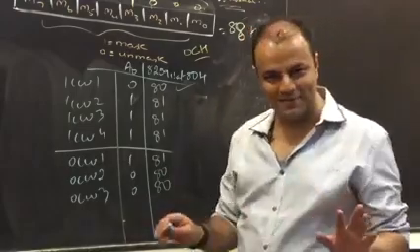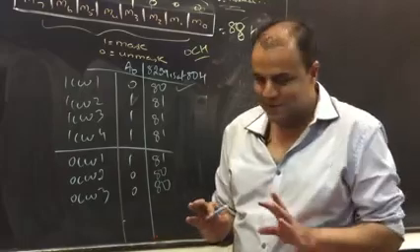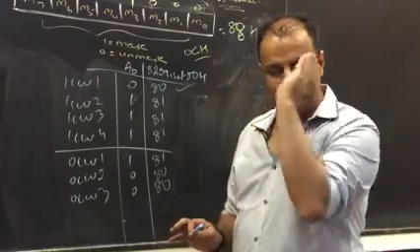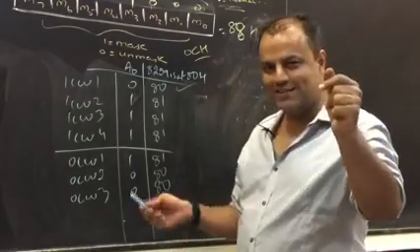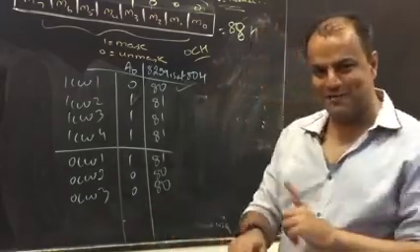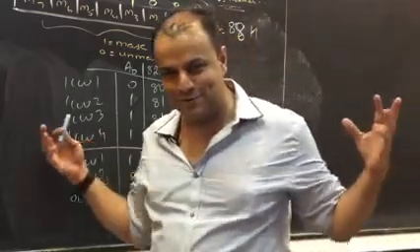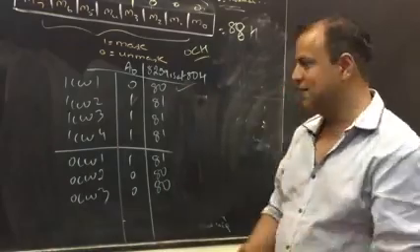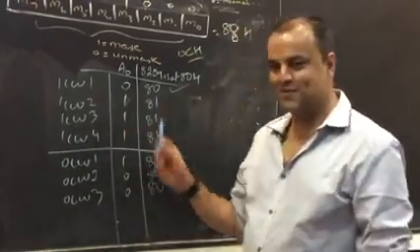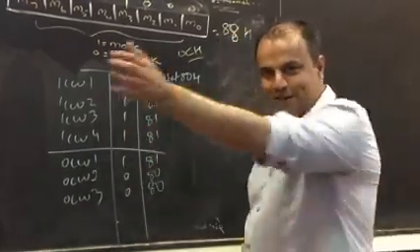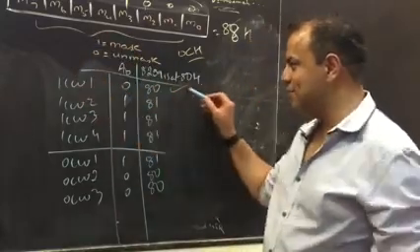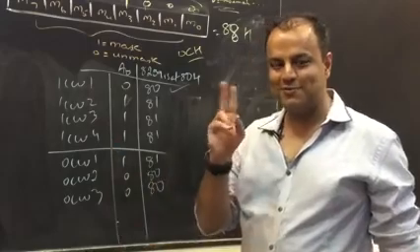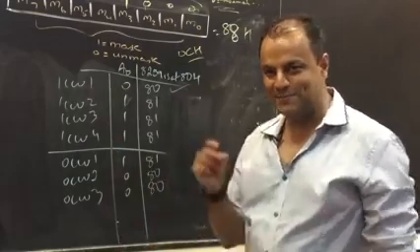Good. So have you identified it? Yes. Will you mistake it for some other command? No. Once you identified ICW1, forget about it. Get it out of your picture, because ICWs cannot be repeated. Remember 45 minutes back I told you all of this will come back together in the most beautiful logic you've learned from me so far. So pay attention. Once you identified ICW1, forget about it. Now ICW1 cannot be repeated, so it won't come back now. So now you're left with 6 commands and you still have 2 addresses, 80 and 81, to identify them.